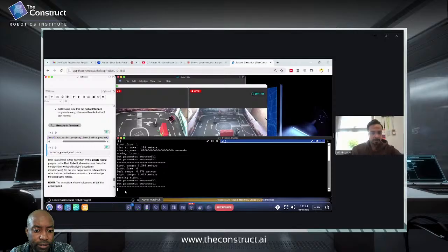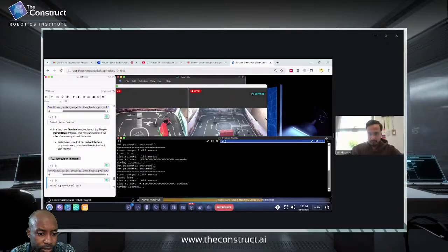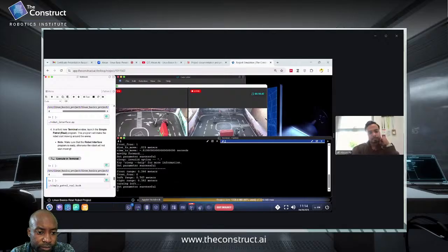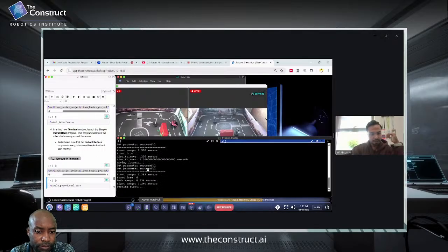Yeah, concurrently, so you can see it's running. Oh, you integrated it into one script. Okay, that's good. So it's basically detecting the obstacle, and if there is some obstacle, it will avoid it and try to move right or left according to the conditions. But first, it's scanning its environment, getting the front range and the front free distance to move, how much distance it has to cover, and the time it will decide based on the bash script we have written.